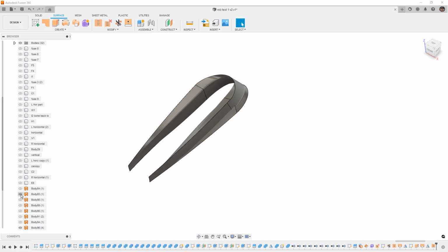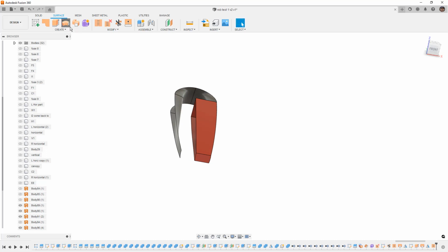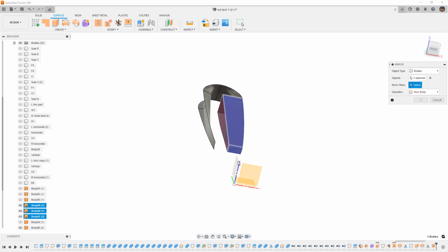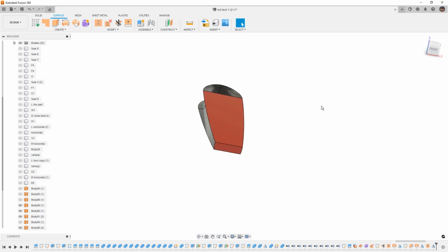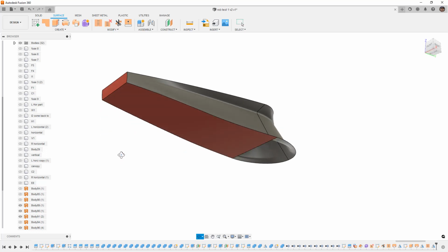And we do have these other surfaces that we did create. So if we can find like this upper surface here, let's go ahead and find that front piece. Let's find the inside piece. So this last bit right there is that. And what we want to do is we want to mirror those to the other side. So we're going to mirror all of these different little surface bodies across that midplane. When we select join, what ends up happening is Fusion is going to stitch those together. And you can see it even did a really nice job of getting rid of that mid seam.